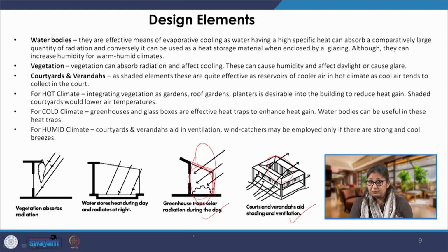In extremely cold climates, you would find that they often have a glazed balcony or bay windows, which bring in a lot of sun, and during the night they would block it by very heavy thick insulating curtains or some sort of covering, which will stop the heat from going from inside to outside. So, during the day bringing in the radiation, during the night stopping the heat loss.